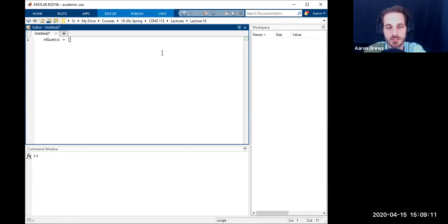The first thing that the solver needs is always a guess, right? If you have no idea where to start guessing, pick the inlet conditions. So initially I know that there is 8.5 moles per minute of A and no B, so I'll just guess that it's going to be something like that. And then I know what MATLAB is going to have to do is say, give me fsolve and solve the function I have to write.